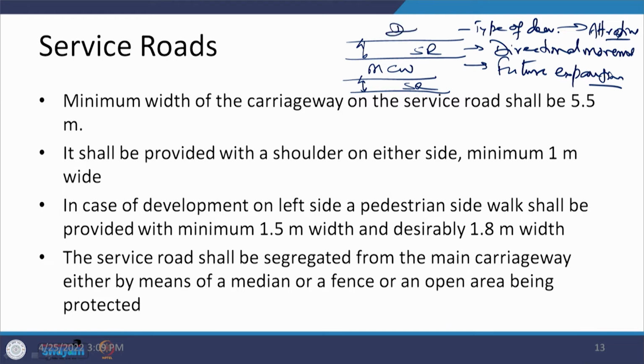So, whatever is the development which is there, if it is just at this edge, then there is going to be an induced traffic because of that. Now, if we are trying to see that this should provide a facility in both the directions, then the width is going to be different. If it is not so, if traffic is not so high at the moment, then we can probably look at some intermediate condition.